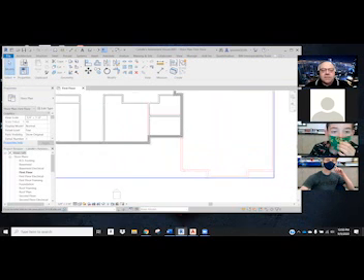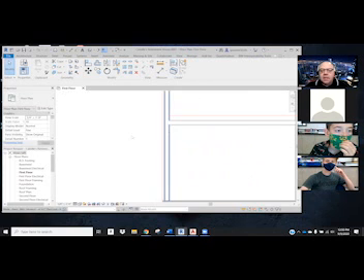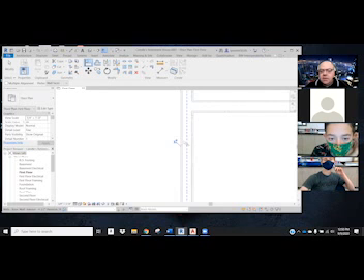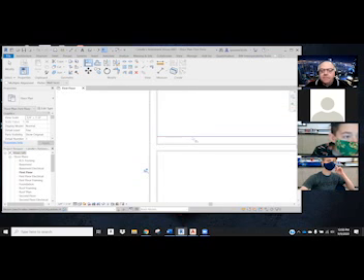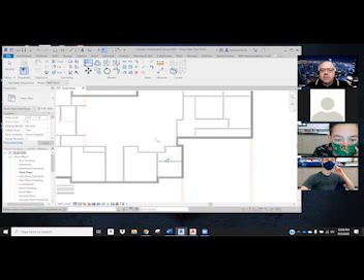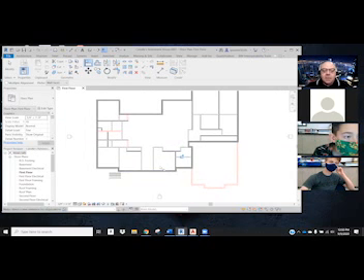All right, I need to go fix that wall that I messed up here. Again, I'm just going to use that align tool. Select the AutoCAD file and the gypsum board outside finish layer to put things in the right spot, and just to clean it up real quick so everything's nice. I need to create my plumbing walls, and I have two of them. One of them is still showing on the screen. The other one has not been drawn yet. And so that's why I'm saying I missed some walls.